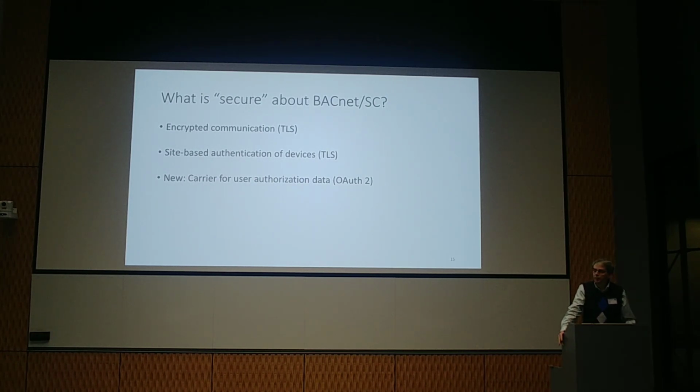So how is this going to be accomplished? You'll be using site-specific certificates that will be installed in each of the BACnet SC devices. And that will allow the other devices in the network to determine whether this device is part of the system or not. So you need to have the right kind of certificate in order to join the network. So I won't be able to just plug into the BACnet Explorer or something and peek around in the network unless I have the right kind of certificate installed in my PC that's running BACnet Explorer.